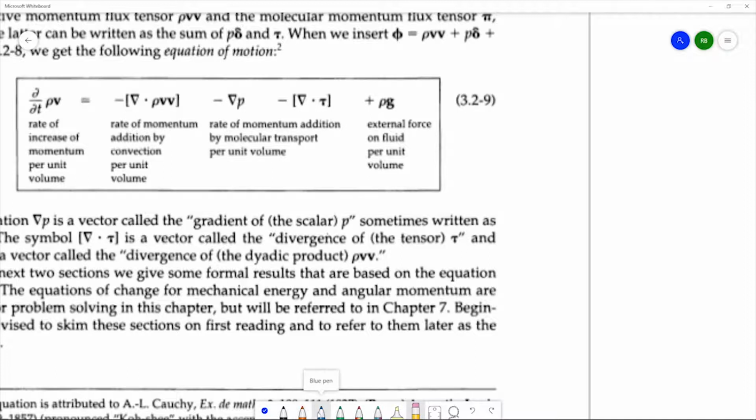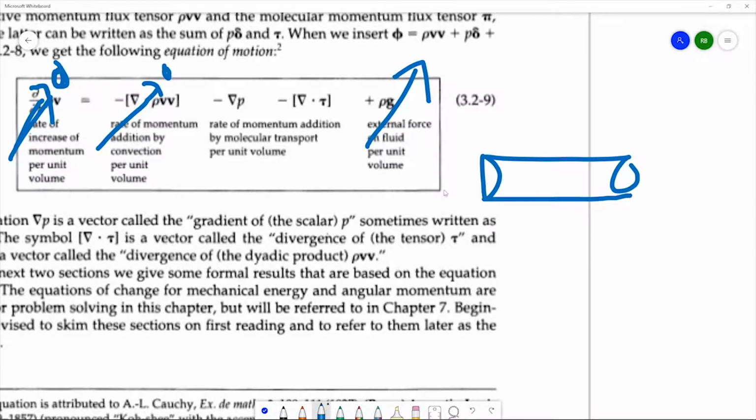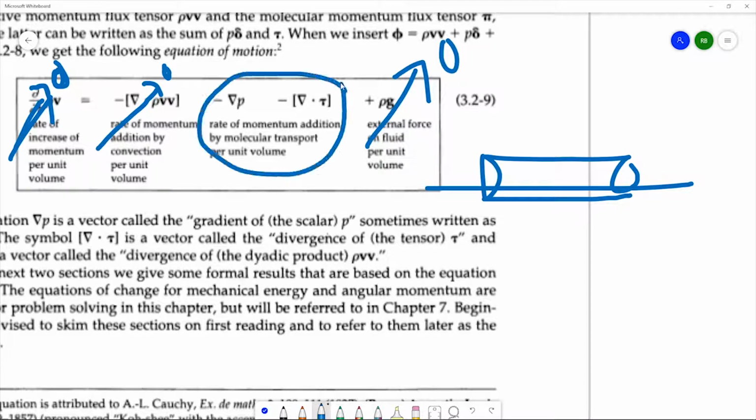So for now, let's say generally you do steady state balance. Okay. So this term will become zero. If you're doing steady state balance, there will be no accumulation, right? So you can directly strike off this term to zero. Suppose there is no convection, so you can directly give zero. Suppose there is no gravity. If you are considering flow in a horizontal pipe, then there will be no gravity, right? Even if there is gravity, it will cancel out. So this term will become zero. Okay, so we are only left with this. So you can make assumptions to this equation and simplify it accordingly.